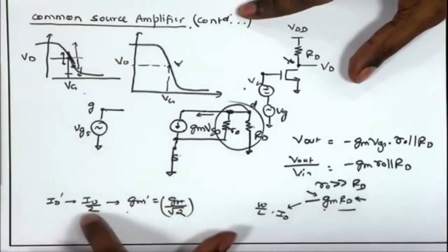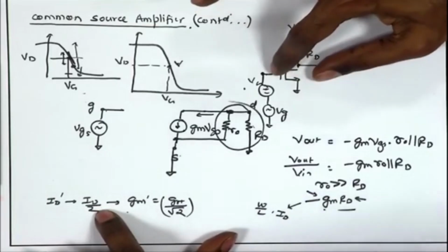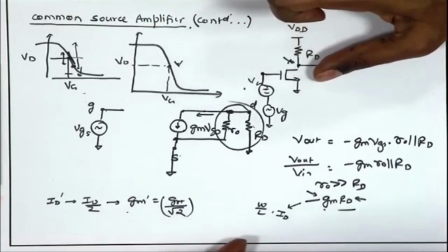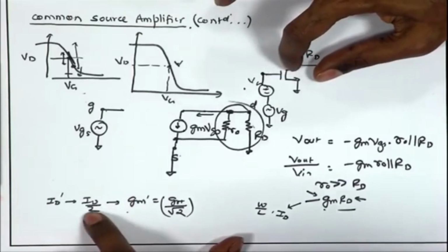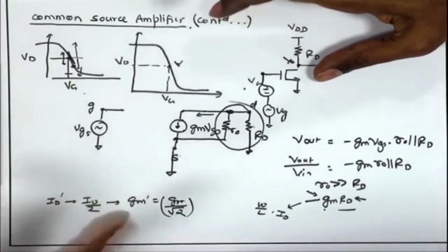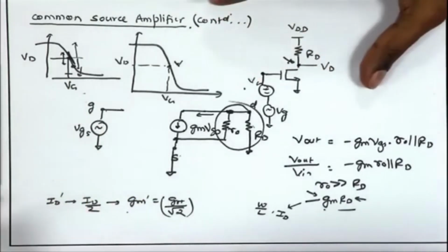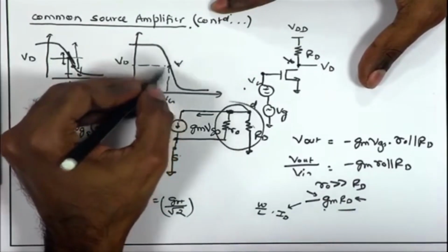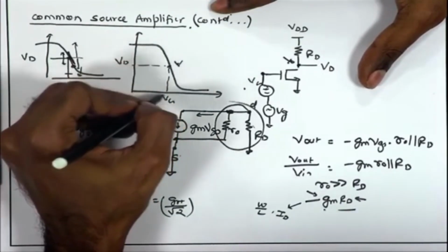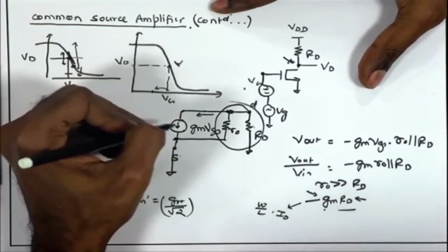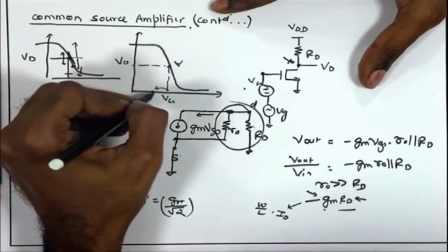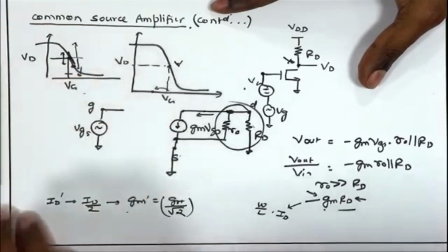current by half. So, basically that means that for this MOSFET, if I follow square law, I have to reduce my Vg by some amount. So, that (Vgs minus Vt) square is reduced to half, or the DC current is reduced to half. That means of course, I am shifting towards lower values of Vg, I have to reduce my Vg. So, in order to reduce the Vg,